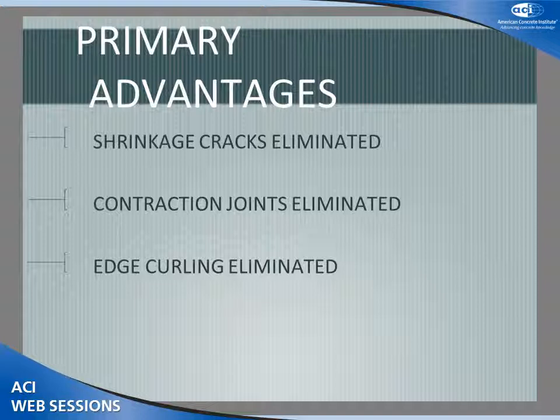As pointed out in the earlier presentation on contraction joints, the elimination of the concrete shrinkage means that contraction joints are no longer needed. The cost of installing contraction joints can be saved. With no joints to be sealed, green construction points can be earned by not using chemical joint sealants. The sustainability is also increased since there are no joint maintenance requirements during the lifetime of the structure.